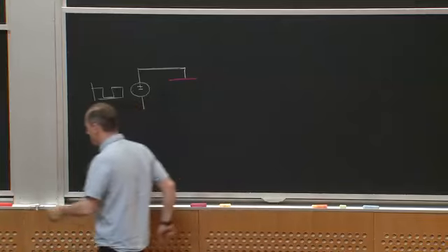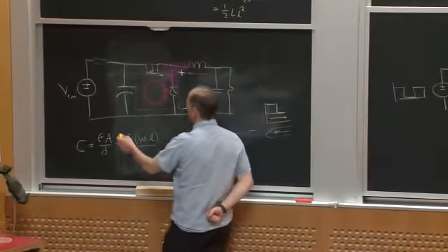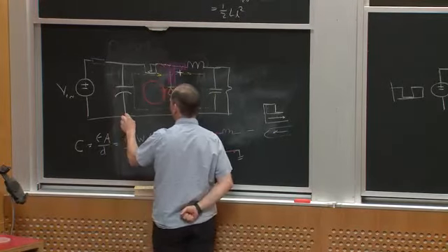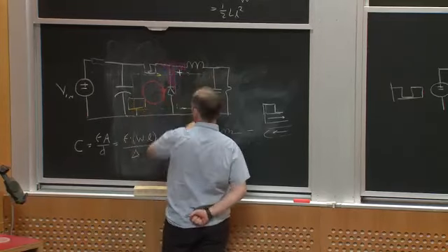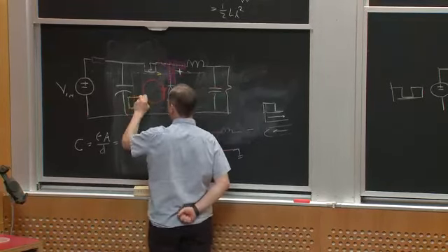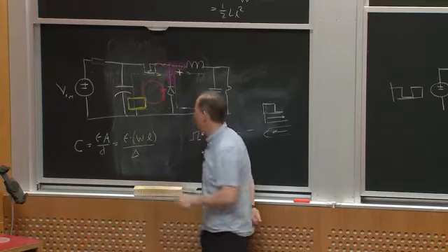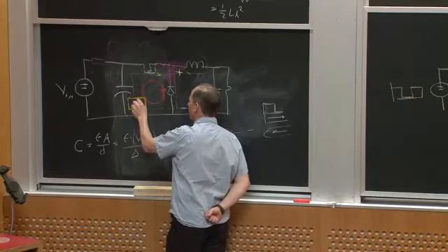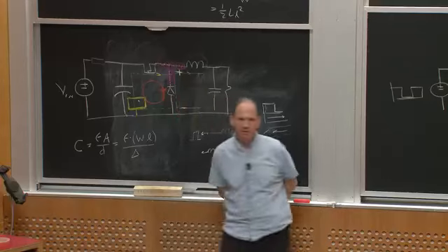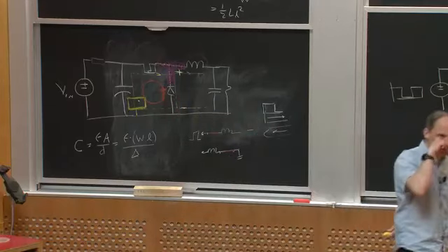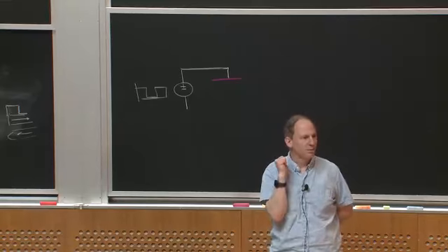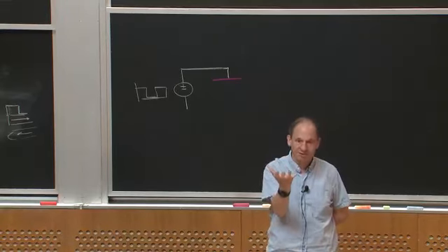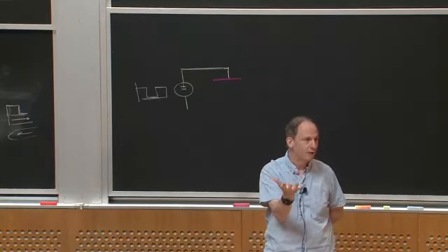But imagine nearby in my circuit, for example, I have some control circuitry down here. It's ground referenced, right? I have drivers and sensors and comparators. They're going to do all the computation for me, right? And maybe within this, there's some very sensitive node. Maybe that's the input of a comparator, or right where my error amplifier, my op amp is, and I can have some very high impedance nodes, right?